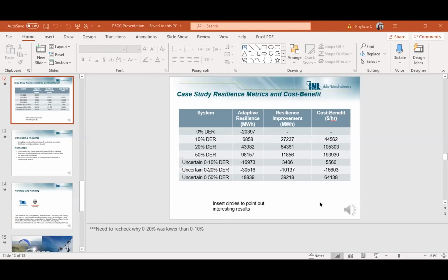One second, I'm just going to read that. Yep. So yes, this has been pointed out to me before. The DERs are modeled dynamically, so you can have a reduction, and then they'll also react to the swings because it's modeled with the DER-A PowerWorld model. So they will react to the voltage and frequency swings, and that will cause the upward swing, which will look like a demand was lost, but it was actually the swing of the DERs.